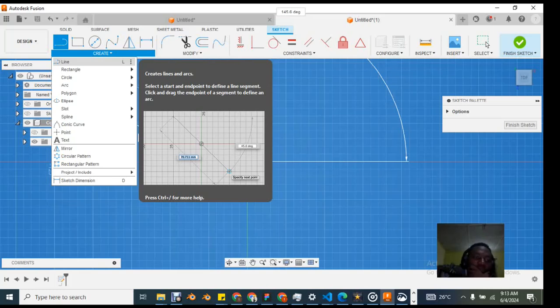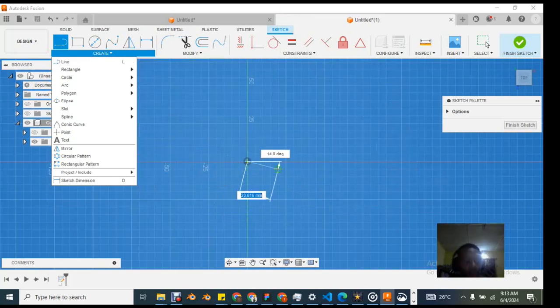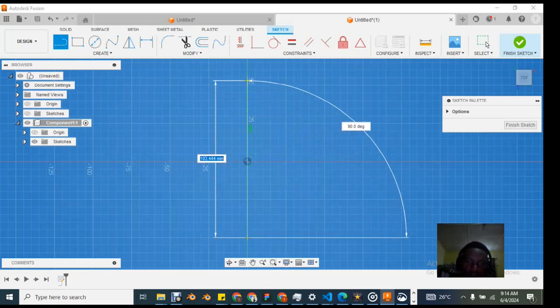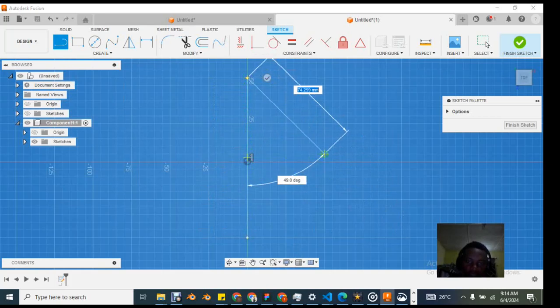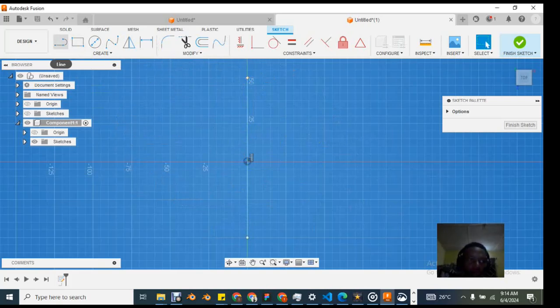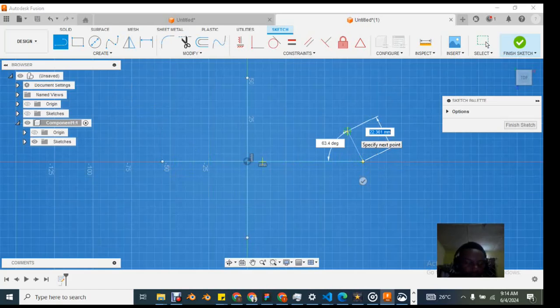So now let me escape. Something I want to show you first of all. If I click my L line, I come here, first place, you are seeing. If I want this line to be straight like this, I just create this and create another one here. Are you seeing what I just did? Escape, L, create a line, click here, and I click here. So I'll be able to create it.